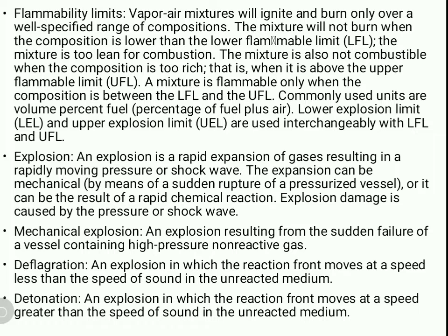Now what will happen if the vapor composition is low? It will not catch fire, and when the vapor composition is very high, it will also not catch fire. So two terms are very important to study: LFL, the lower flammability limit, and UFL, the upper flammable limit. The lower flammability limit is the point where the mixture is too lean for combustion, and the mixture is also not combustible when the composition is too rich.